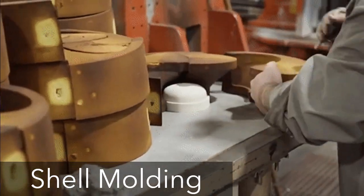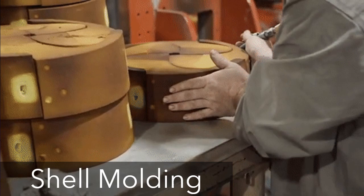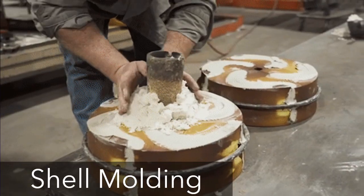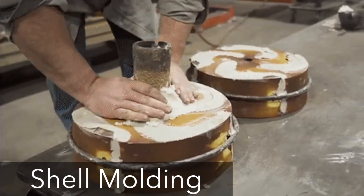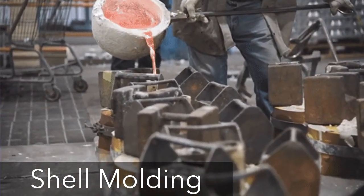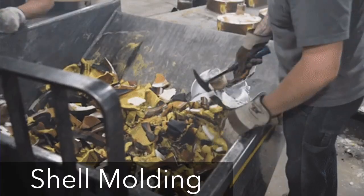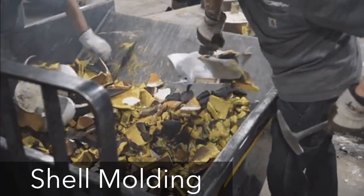The two half shells made in this manner are bonded or clamped together to form the mold. They are prepared to be filled with the molten metal. Fill with the molten metal, leave it to cool down and solidify, and then the mold is broken up to get the cast material.